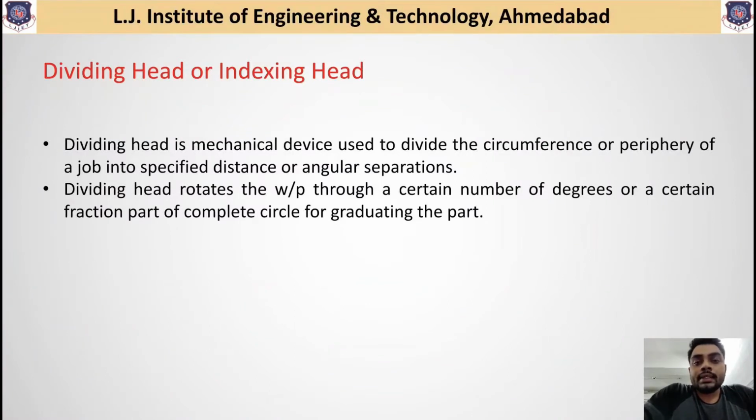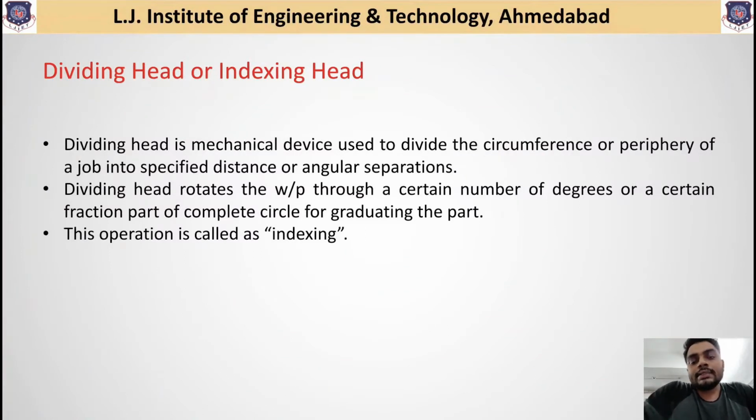To obtain that equal distance during the machining operation, this type of dividing head or indexing head is used. This process of dividing the circumference or periphery of a job into a specified distance or angular separation is called indexing.